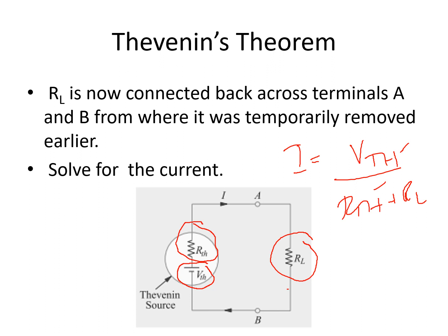So that is how you perform Thevenin's theorem. It says here that any complicated circuit can be reduced to a simple series circuit having a resistor RTH in series with your VTH, or your Thevenin's voltage. To illustrate this further, let us have an example.